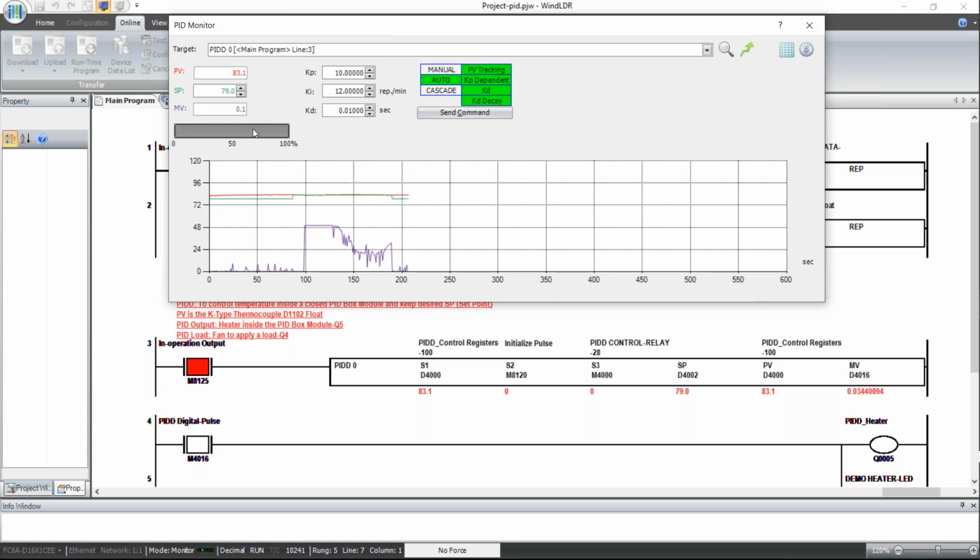So now if I go back to the set point, go to 84, or let me go to 85 actually, 86 maybe. Now guys, you see how fast I went to 100%? Because I think the KP is way too hard. I'm going to go back to 2.5 now. And now at 2.5, I'm at 86.